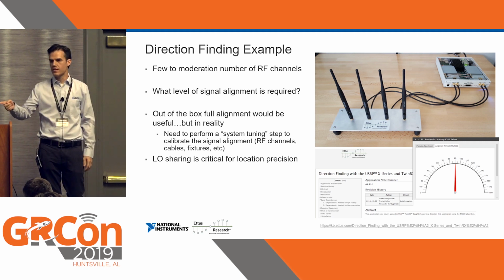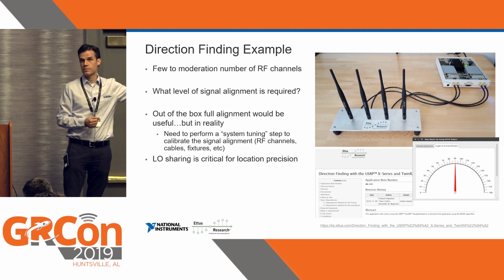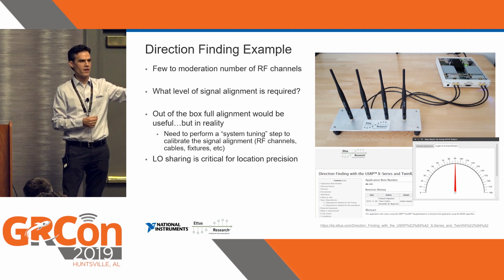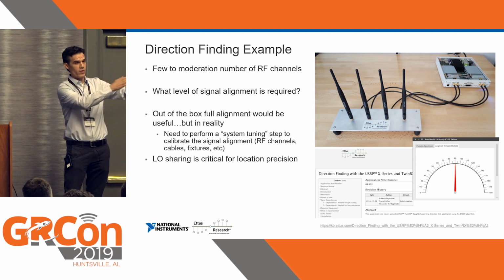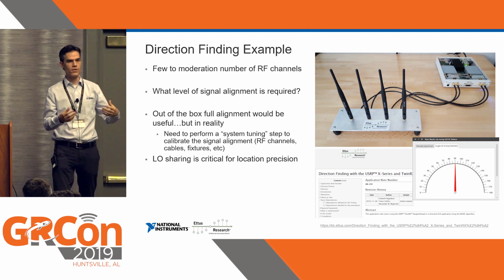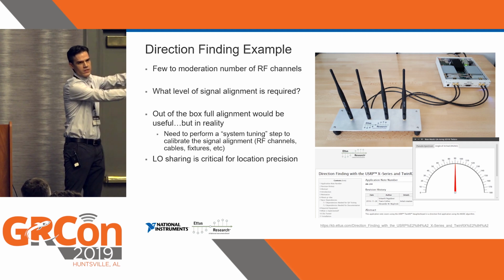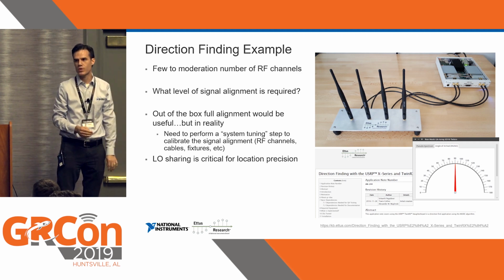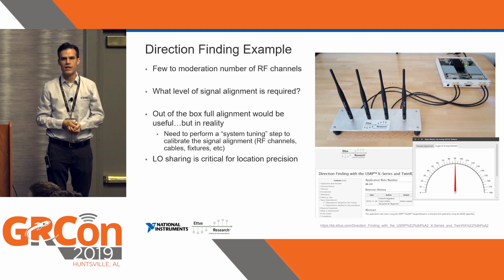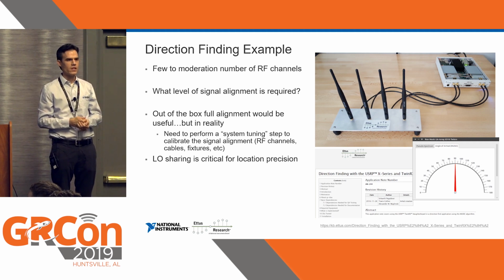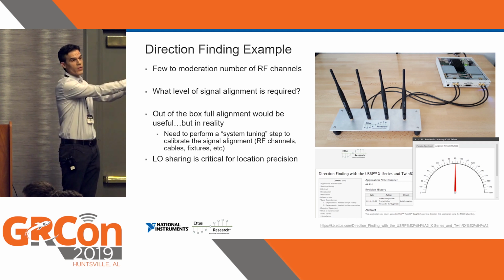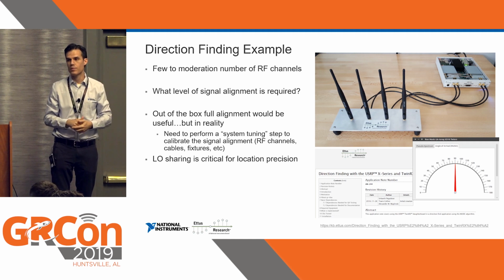Well, if that signal is coming in from your right, then the antenna that's on your right is going to detect that RF energy first before the antenna that's on your left will detect it, right? So you can get a sense of, oh, okay, the wavefront's coming through, and then tuck, tuck, tuck, tuck, tuck, tuck, tuck, it hits all the antennas, one right after the next. And so this example uses an algorithm called MUSIC that basically looks at the time of arrival of when the signal hit each of the antennas to figure out the angle of arrival of where that was coming from.